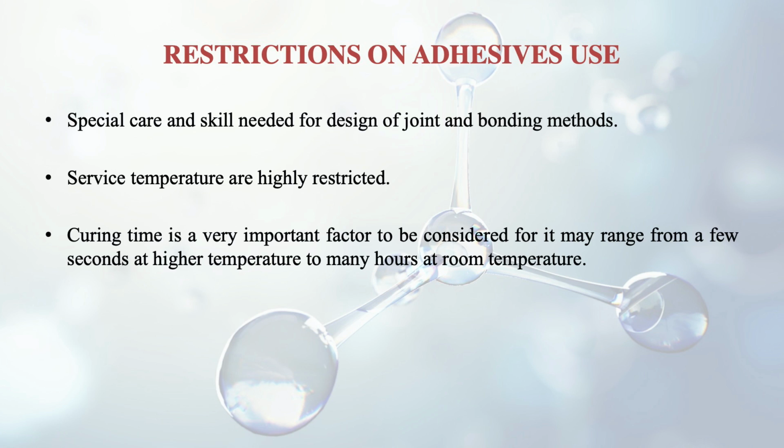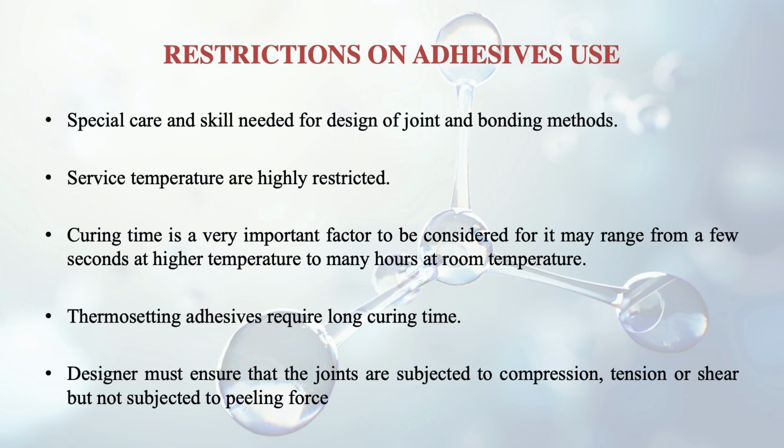And a restricting factor, thermosetting adhesives require long curing time because they are of higher strength. And our designer or whoever is working on that must ensure that the joints are subjected to compression, tension or shear, but they should not be subjected to peeling type of force, meaning a force which tries to remove that layer should not be applied on it.